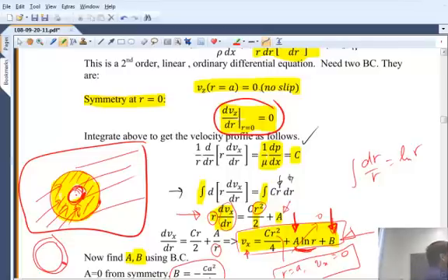Would that velocity profile be fine for non-laminar flow? No, that's a good question. That is not valid for non-laminar flow. The reason is for non-laminar flow, the assumption of V theta and VR equal to 0 is not valid. You will have VR as non-zero, V theta as non-zero component. Experimentally, that's what we find.